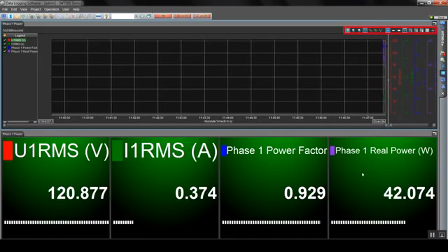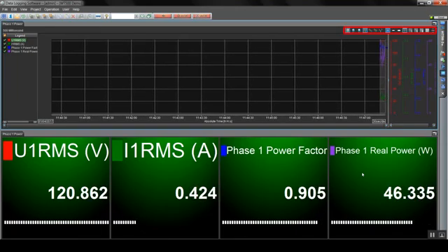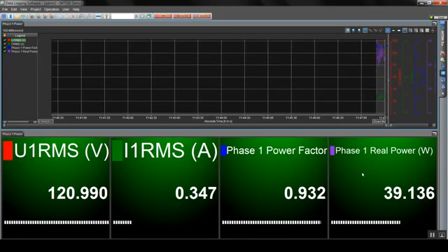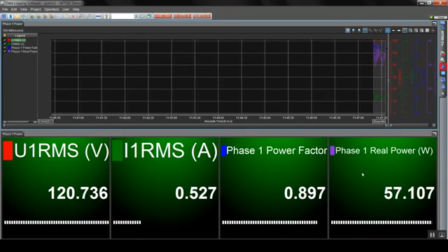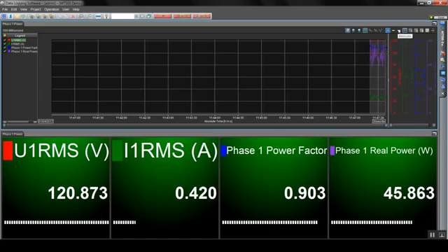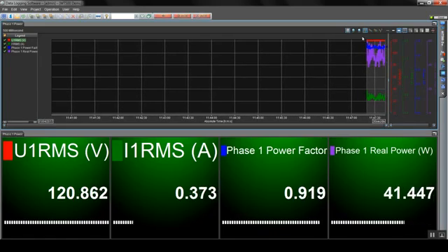We can now customize the display as we see fit by adjusting the grid type, magnification, line thickness, scale, alarm condition, and color, all while monitoring is occurring. This can be done by selecting the wrench icon, selecting Display and Display Group. Additionally, the layout can be adjusted by navigating to Acquisition and Monitor and adjusting the number of panels as well as the horizontal versus vertical layout.